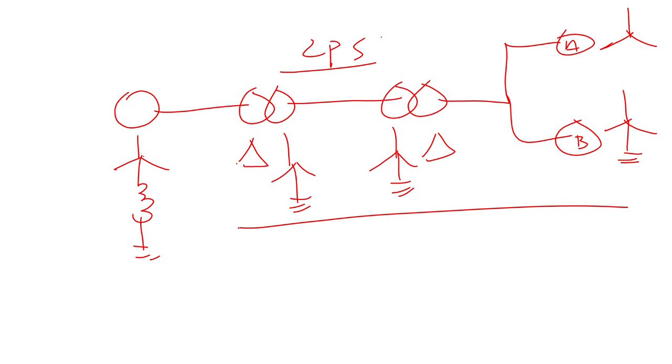So I'm going to start off with the generator. The generator is star grounded. Here is J0.516. So I'm going to bring the reactance. I'm going to connect it to the line because it's grounded first and bring the reactance of the generator. Then I bring three times of the J0.516 into the zero phase sequence diagram because the reactance is inside the star point. So it will be in zero phase. Good. Then I go to the transformer.